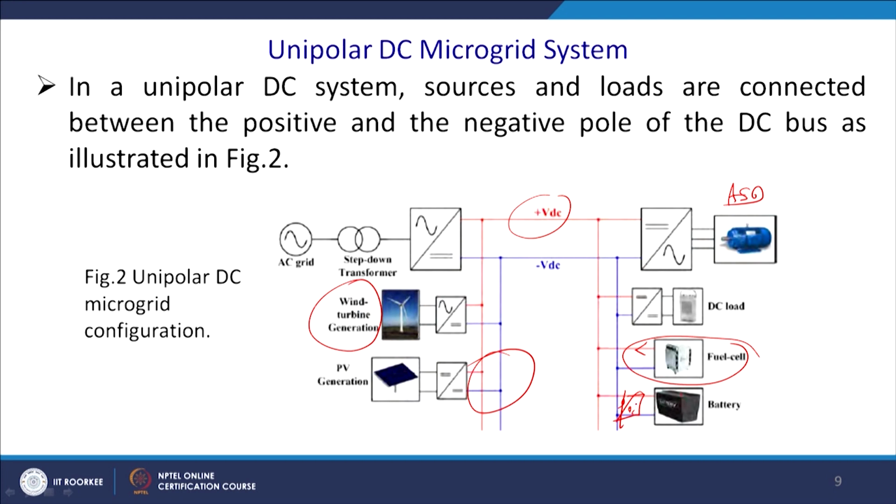You can see that a simple diode can operate, because charge can flow this way, and once it is on, you can turn on the mechanical switch for charging, and for discharging you can take a different path. But in general, to control actively we require to put a bidirectional DC to DC converter in front of the battery also.